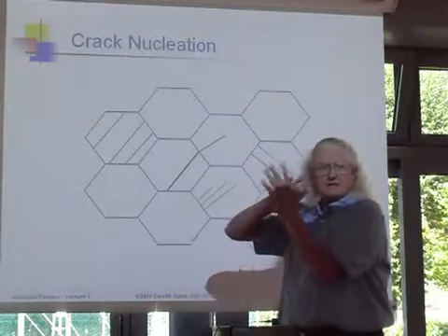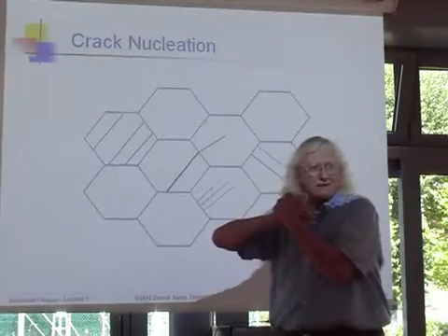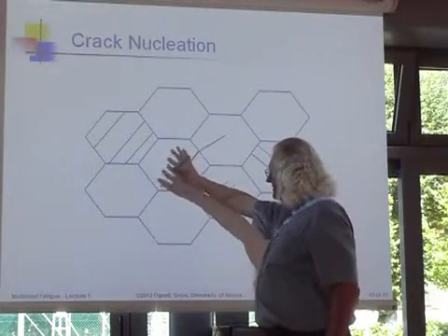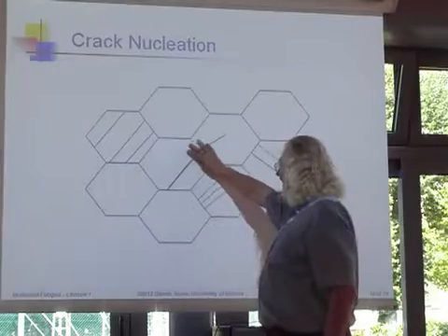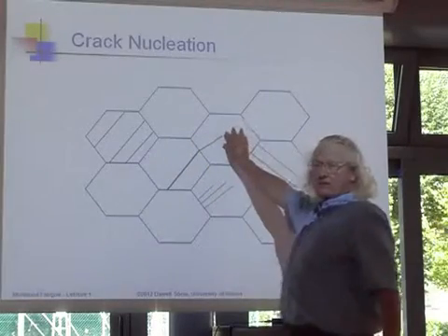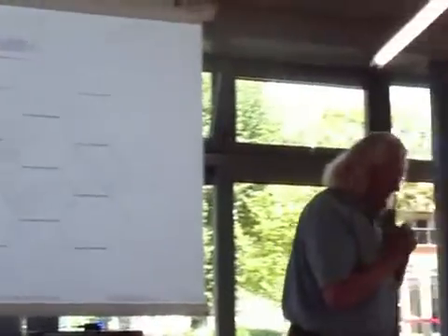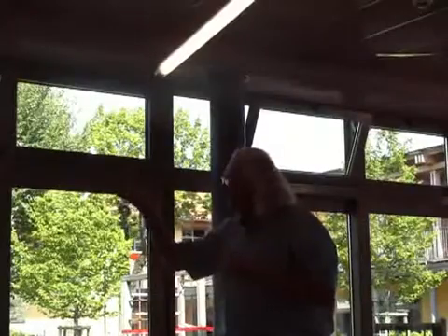So to get a fatigue crack is not so easy. The applied stresses have to line up to activate slip systems in a grain, and it then has to propagate that into the next grain. And this is exactly what Ewing and Humphrey found more than 100 years ago. Now, as I tell you this story, then you can see immediately it means that fatigue is a statistical process.